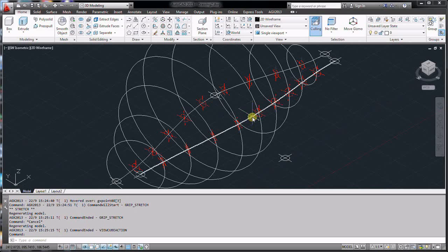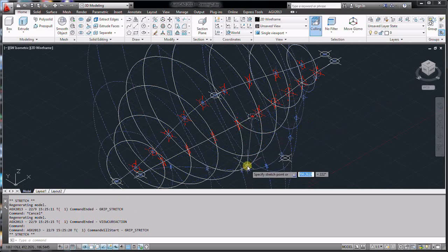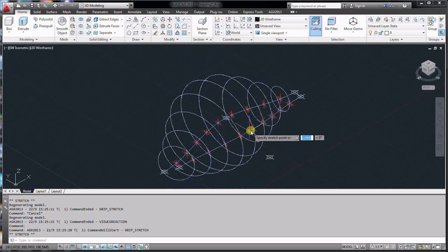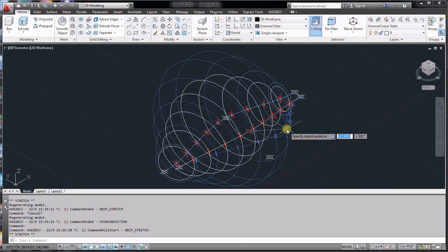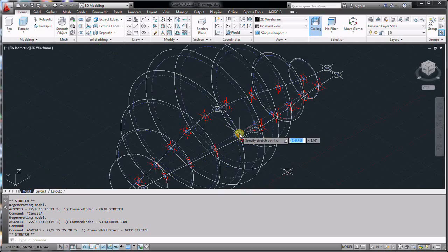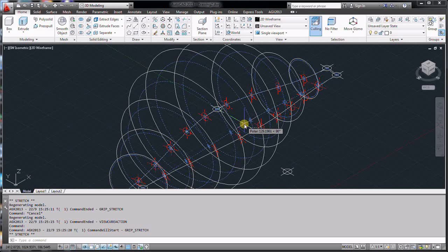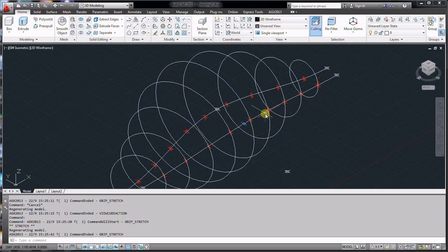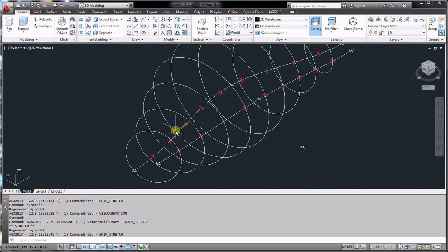Also again, just to show you that this works in 3 dimensions as well, whereas the standard AutoCAD parametrics don't allow you to do modifications in 3 dimensions. So you can change your design in real time just to see what the results of your changes are going to be. This is obviously quite helpful in many cases where you try to do this sort of geometric setup with vanilla AutoCAD.